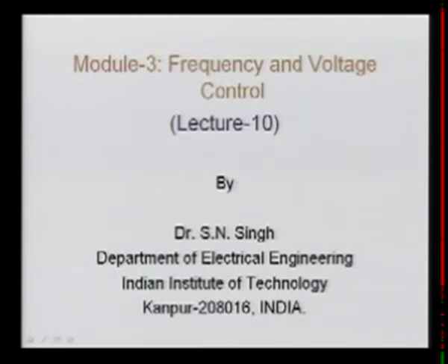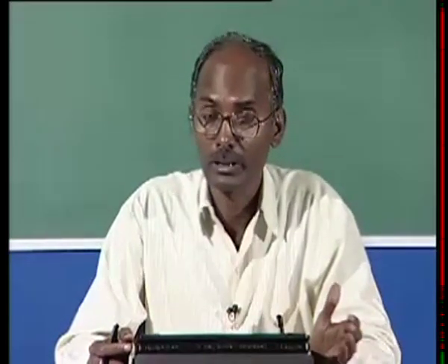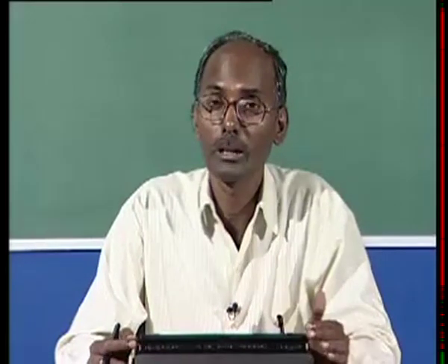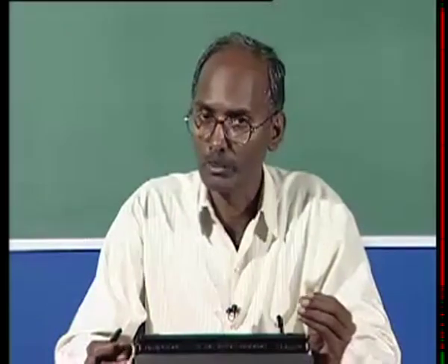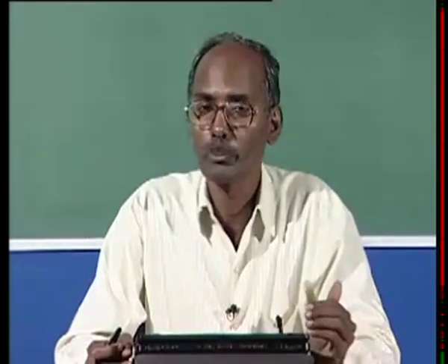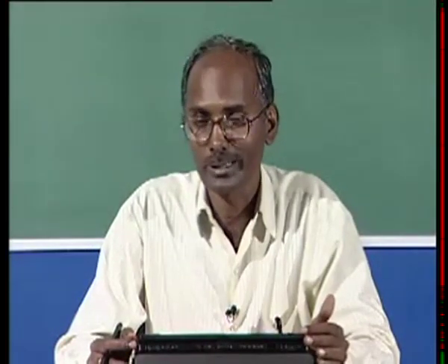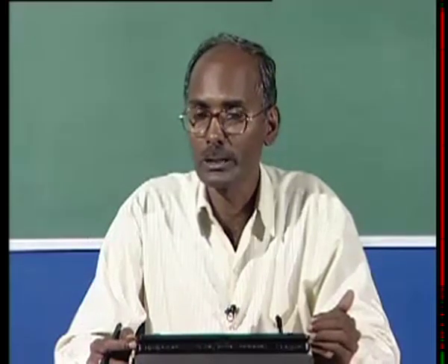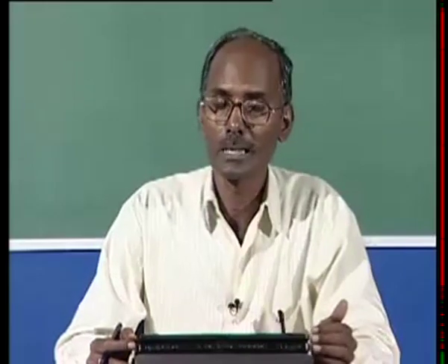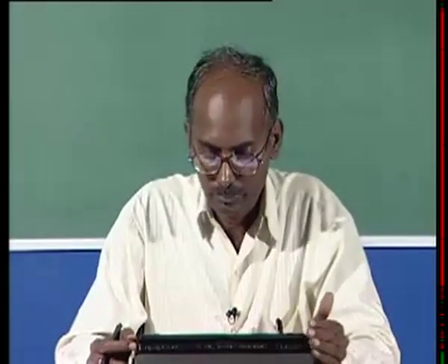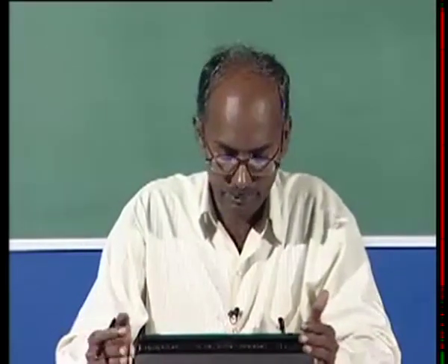In this lecture number 10, I will be discussing what I said in lecture number 9: that shunt controllers will improve your steady state limit, your transient stability limit, your voltage stability limit, and will also damp out the power system oscillations. So all these four advantages the shunt compensation, that is the shunt FACTS controller, will provide. We will see how they change the limits by controlling these values.